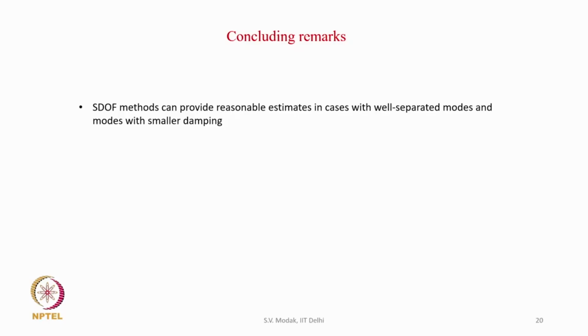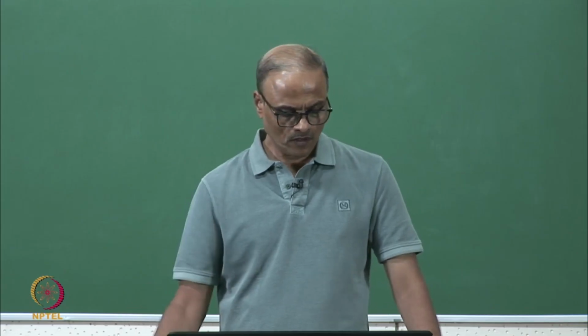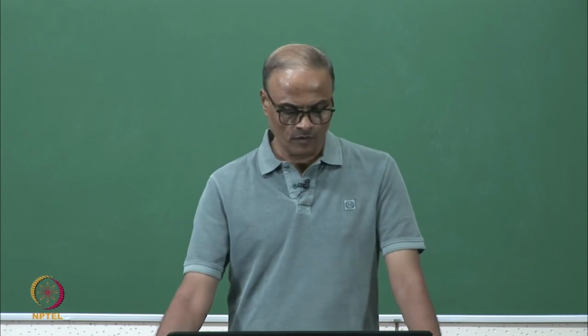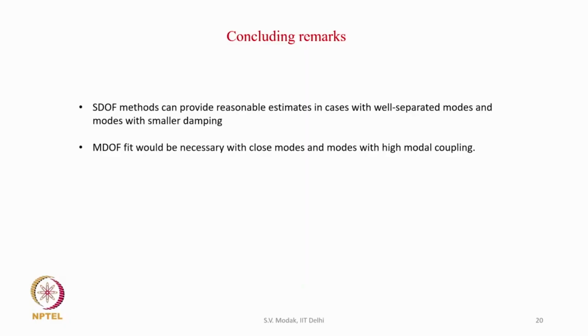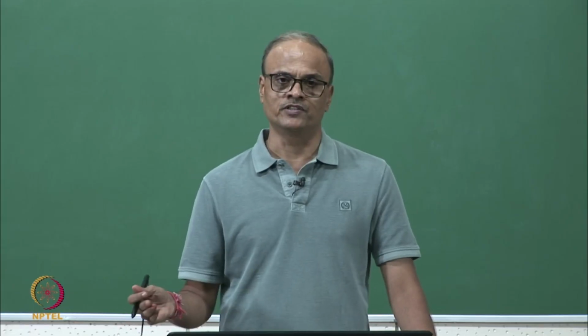So, the first observation is that the single degree of freedom methods can provide reasonable estimates in cases with well separated modes and modes with smaller damping, correct. In this case the single degree of freedom assumption would be valid, and then they can provide reasonable estimates of the model parameters. Now, multi degree of freedom fit would be necessary with close modes and modes with high modal coupling, because in such cases the single degree of freedom assumption would not be valid, and therefore multi degree of freedom fit would be essential.